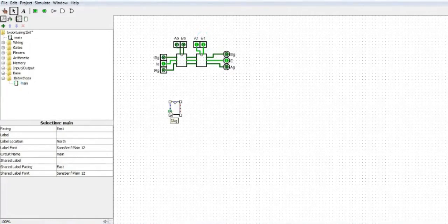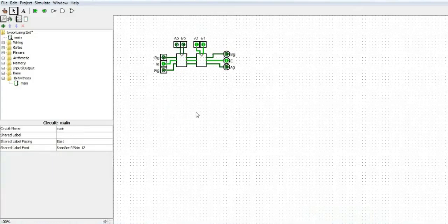So this is the A greater cascade pin, A equal to B cascade pin, then B greater cascade pin, then A input and B input, then B greater output, A equal to B output, then A greater output, right? The same I have taken as two copies so as to develop a 2-bit magnitude comparator using the 1-bit magnitude comparator with the cascading input concept, right?